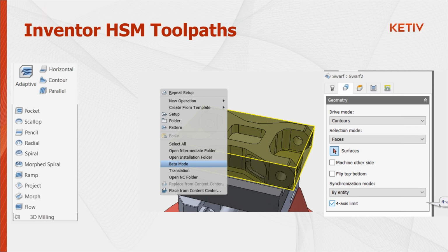Now, it's not going to be true 5-axis. It is going to be 3+2 machining, right? So what that means, again, going back to positional, it's going to position the part in a certain orientation, depending on how your feature is essentially built onto the part. It's going to make that face or that feature perpendicular to your tool axis. It's going to machine that feature, and then it's going to rotate to the next operation and then machine that second feature, right? So again, you do have options or capabilities within the 3D toolpaths or even 2D toolpaths as well, to have some sort of 3+2 or simultaneous 5-axis toolpaths.